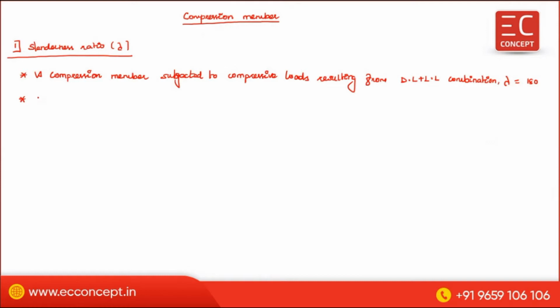Next one, a compression member subjected to compressive loads resulting from dead load, live load combination, this is due to wind load or earthquake load, lambda, which is equal to 250.